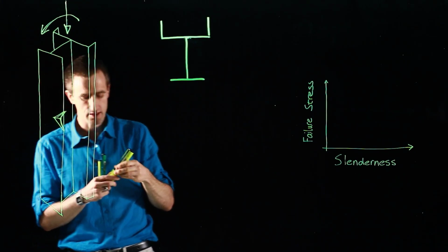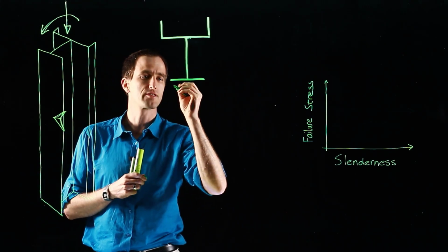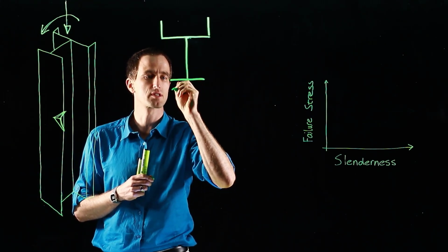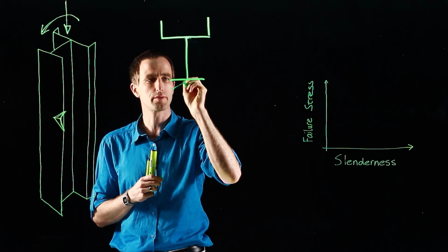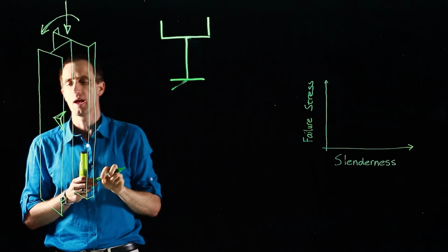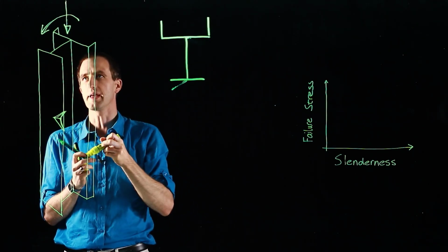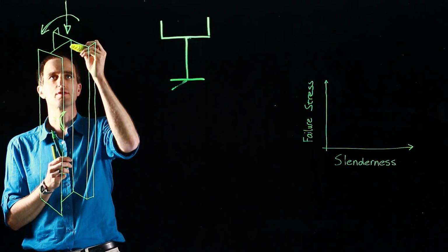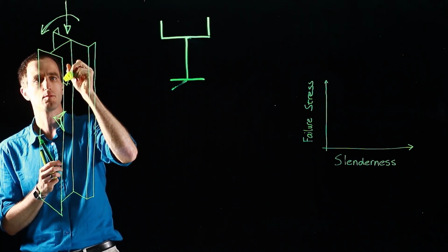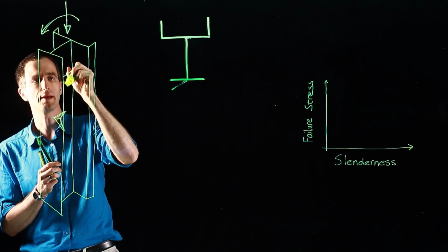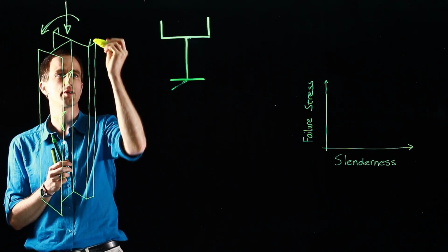And so if we had a look at a cross section, I've drawn it on this bottom flange, so we would have something that looks like this going there. And this would then be how it buckles. And then we can have the same thing with the web. Somewhere along the length, the web then experiences local buckling. I'm going to draw it there, for instance, where a section of the web experiences buckling, or this other little flange could even experience local buckling.